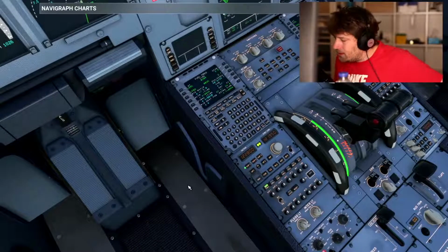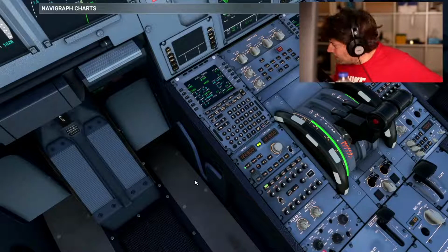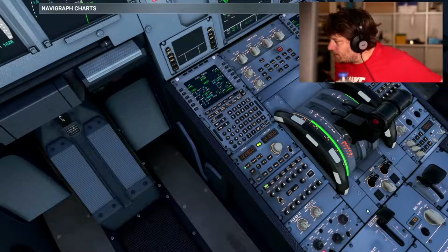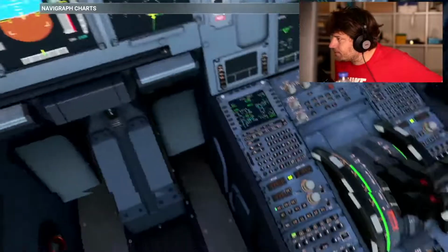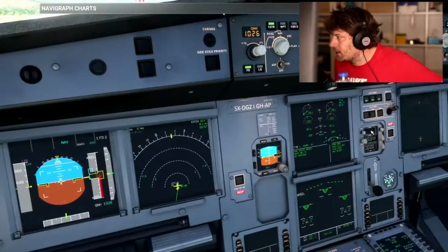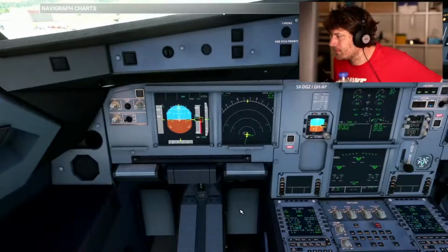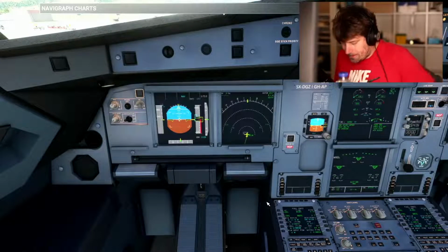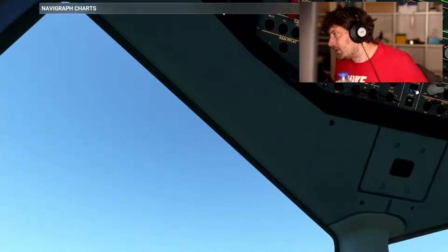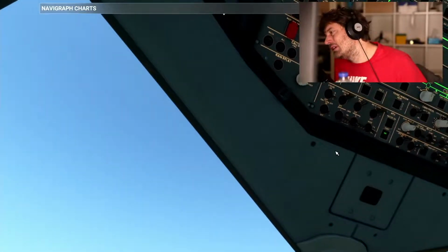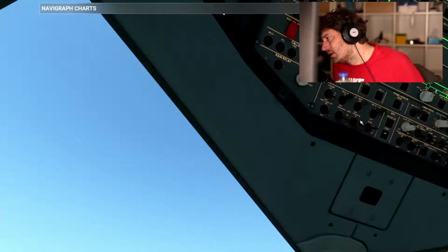Let's put the flaps to takeoff and arm the spoilers. Put the auto brake to max. Turn off the APU. Turn off the APU bleed as well. Nose wheel lighting to taxi. Runway turn off lights on. Strobe on.